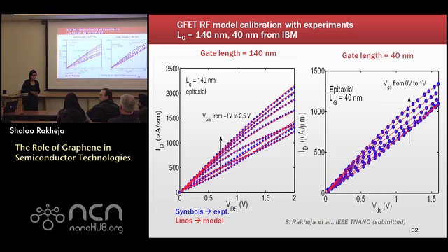For these different channel length devices, do you use the same contact resistance? Well, it depends. Once you fabricate it, most of the time we interact with experimentalists to find out if their contact resistances have changed or remained the same. But for some of these devices, we see a little bit of variation in contact resistances. I have an exhaustive table of extracted parameters, which I can show you. The resistances over here were somewhere around 500 ohm-microns, but they go all the way up to 1,000, 1,500. So I've seen a lot of variation.